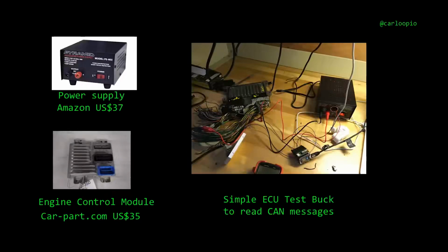You can buy a scan tool for that specific brand and use a Y splitter. Let me show you what that looks like. This is the easiest way to show what a Y splitter looks like.